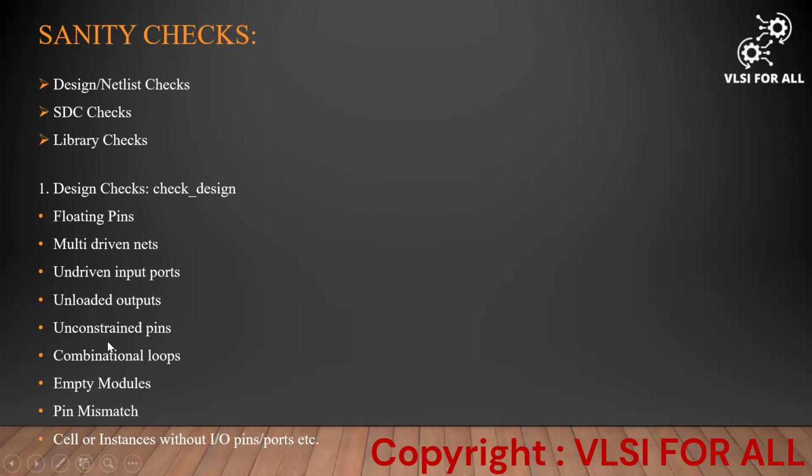The next thing we have to check is unconstrained pins. Unconstrained pins are the pins of the cells in the design that should have some timing constraints on them. Likewise, it has to be mentioned. If not, we have to report that.